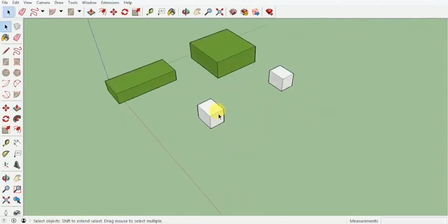This works well when we have one particular type of object and we need to copy it in multiple places. And we have to change it throughout the project, so it will help us a lot. So if we have one particular window and we make it into a component, if our client or anyone tells us to change it a little bit, we will make one change in one of the components and all of them will change everywhere else.